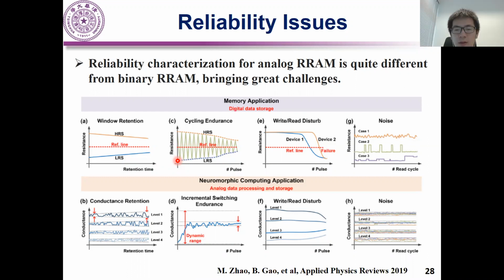Great. We have another question. Are analog RRAM devices fabricated on the same wafer as the peripheral circuit? Because CMOS circuits can also achieve such a synapse function, what is the advantage of your RRAM compared to a CMOS synapse at present? A CMOS synapse can have a longer lifetime and much better compatibility with CMOS devices.